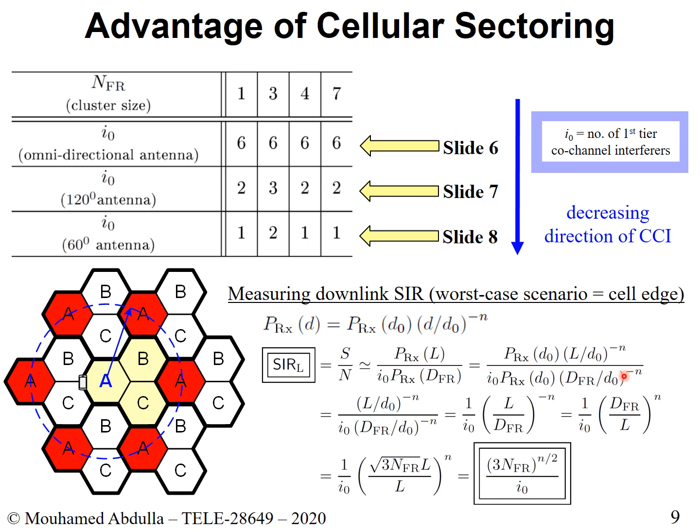And in the bottom, we are interested to find noise and again to find interference. And in fact, we are interested to find the aggregate interference seen by this device. Now, how do you measure the aggregate interference by this device? You could basically measure all the different interferers. So basically, you could measure this distance from this point to the mobile unit, this distance, and so on and so forth.